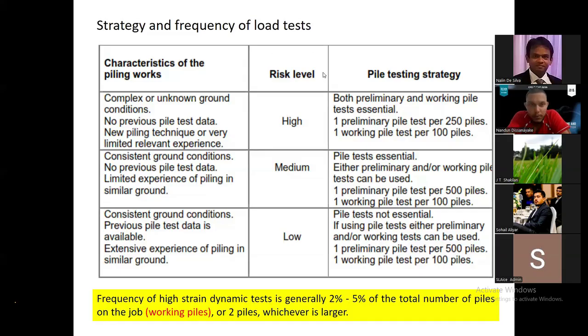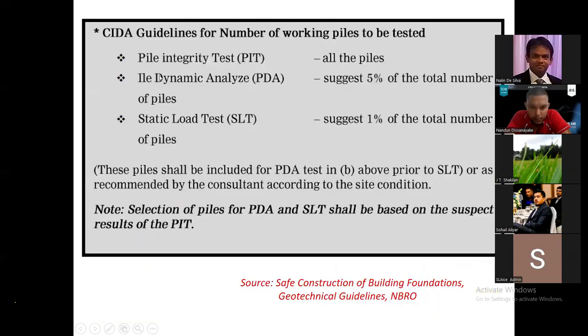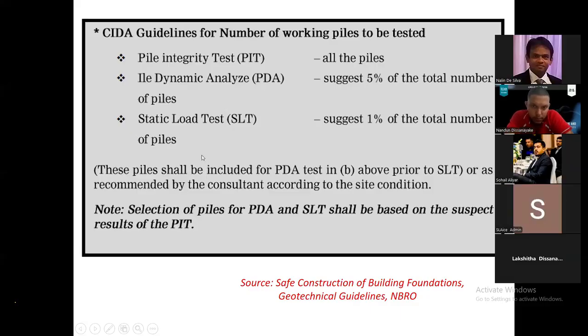According to the Sri Lankan CEDA guidelines, integrity tests have to be carried out for all the piles. Then high strain dynamic load test should be conducted for 5% of the total number of piles. And it is recommended to conduct 1% of the total number of piles for static load test, MLTs. Okay. So this is the strategy for the testing frequency.